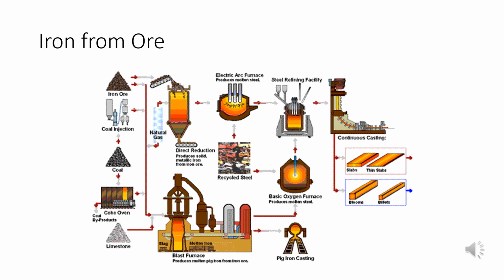The other thing you can do with it is, you got extra iron. You can heat it up, add some limestone mixed with the impurities, and it comes out as slag. Have you ever seen lava rock like in flower beds or something? It's old iron ore slag or steel mill or iron mill slag. Just pour it up into ingots, and those are pig iron. It gets its name because they look like little pigs. But this is how you make steel from iron ore. A lot of energy right here, a lot of energy.